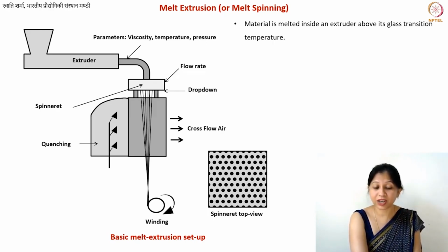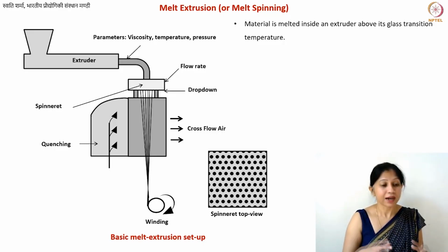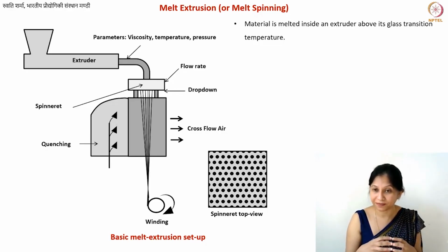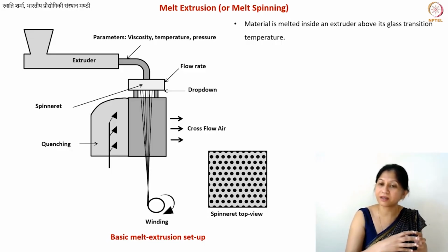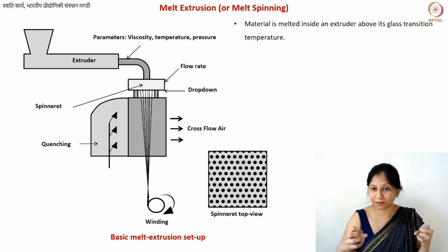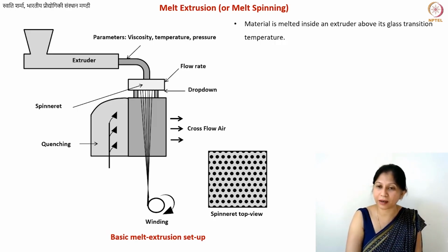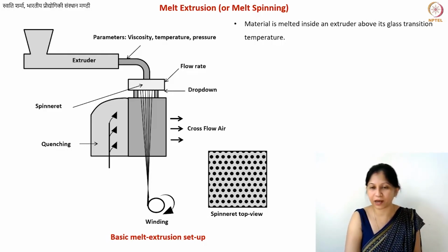What is glass transition? I think we also briefly talked about it during the photolithography lectures. Glass transition temperature is the temperature below which the material behaves like a glass. Above this, the material is sort of melted, or it is not. I don't even know if melting is the right term that we should use for polymers. It's a little bit the flow of fluids. The flow of chains or molecules of polymers has a slightly different mechanism compared to, for example, melted metals. And this is what makes polymers very interesting.